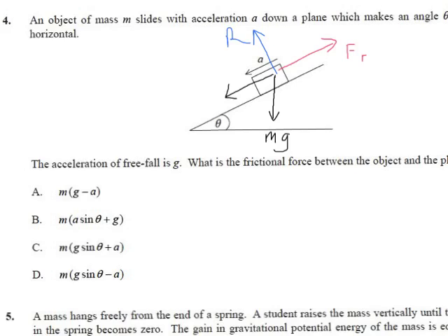Okay, so let's try summation of forces. The summation of forces, by adding the forces acting along the slope, remember we're ignoring R because that's perpendicular to the slope. Now we don't need it anymore. If you just look at what's going on here, I'm going to call this force F. So we have F down the slope minus friction equals mass times acceleration a.